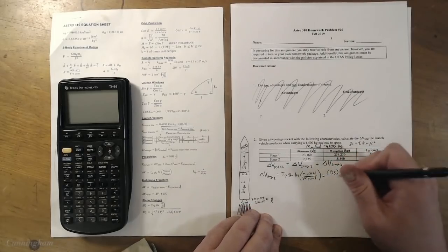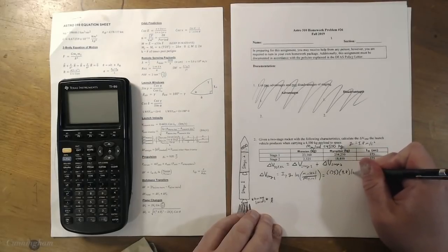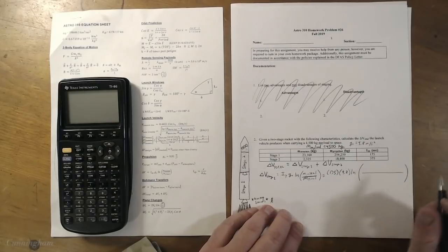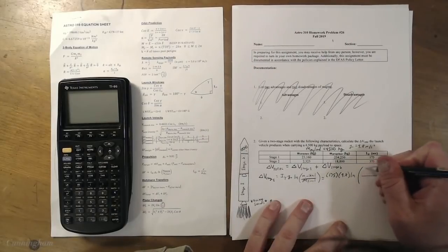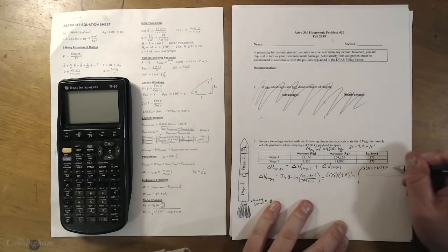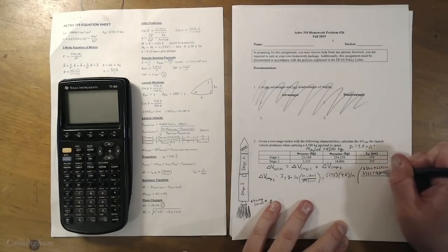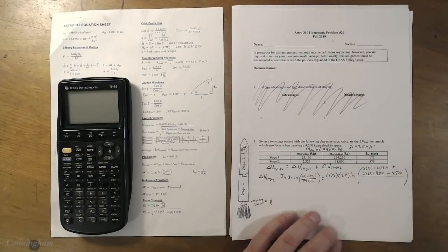in seconds, weirdly, but it's just how we do it. Times Earth gravity, 9.8 meters per second squared, times the natural log of, here's where we make our money. Okay. The mass of everything sitting on the launch pad is, oh boy, I'm just going to start up here, 23,160 plus 254, 250 plus, I'll write it down here, 23, 25 plus 18.8 plus the payload, which is the satellite itself, 4,500.